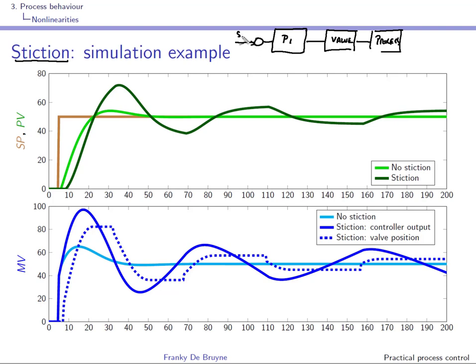And we have the set point over here, and of course the feedback part, plus and minus, right? And what happens is that there is static friction in the valve, so that the output of the controller does not necessarily correspond to the valve real opening, right? Because of this static friction. Here we have a simulation of a closed loop step response.